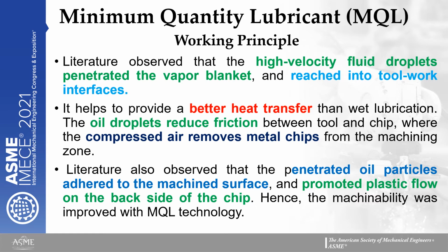It helps to provide better heat transfer than wet lubrication, and the oil droplets reduce friction between tool and chip, while the compressed air removes metal chips from the machining zone. It is also observed that the penetrated oil particles adhere to the machined surface and promote plastic flow on the back side of the chip. As a result, machinability was improved with MQL technology.